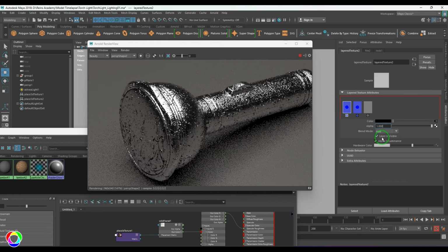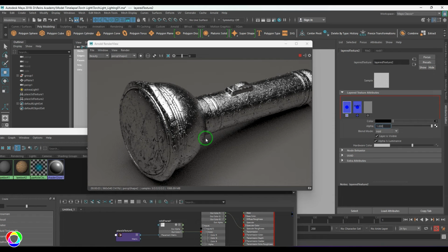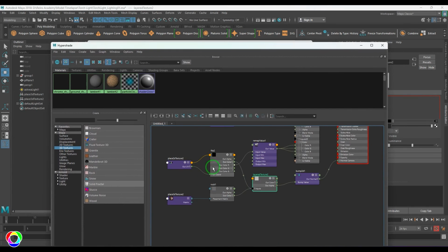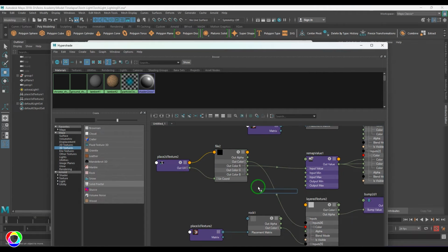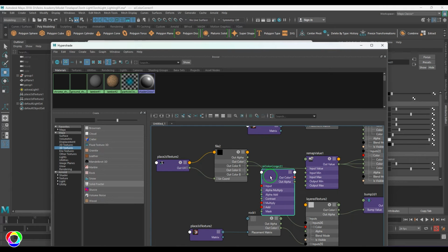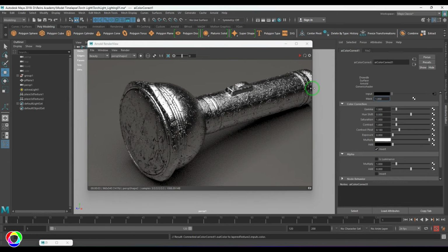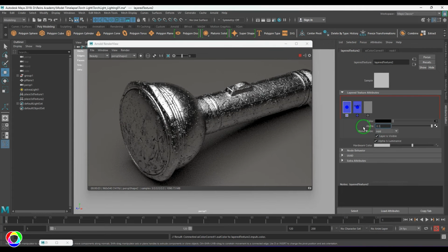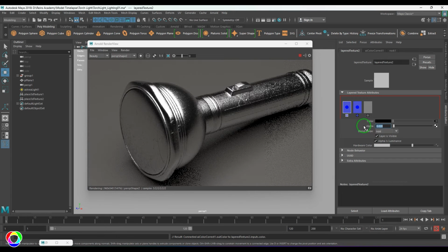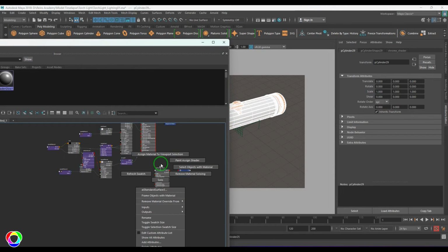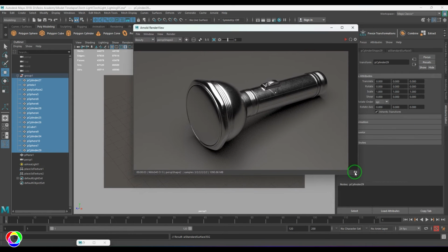Now I'm going to select this layer, make it visible, and here this layer will add a bump. So I need to fix something with this layer. So this layer is connected to the color here. So I'm going to take a color correction node, or we can take an invert texture. We don't have that, so I'm going to take the color correct node there. I'm going to connect this texture here and this one there, and once that is achieved, just switch on the invert, so that brings up the cavities of these scratches. Now let me select the layered texture and bump value of 0.1. That has brought down the bump, so I'm going to take it way down. It should be very low, just a slight hint of that is enough actually. Okay, I'm selecting everything and assigning that shader. Okay, now let's store this one and render it.